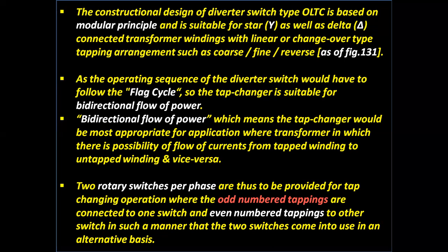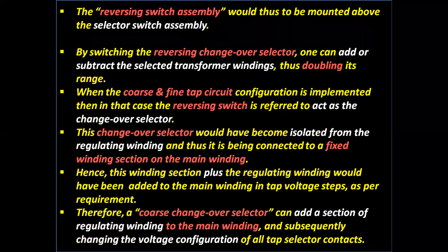Two rotary switches per phase are thus provided for tap changing operation, where the odd numbered tappings are connected to one switch and even numbered tappings to the other switch, in such a manner that the two switches come into use on an alternate basis. The reversing switch assembly is mounted above the selector switch assembly.